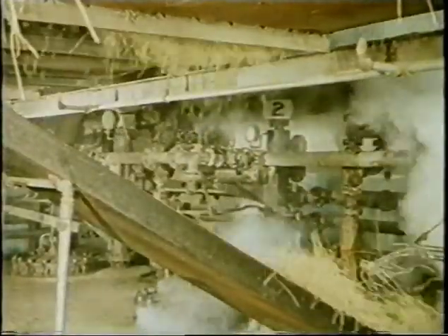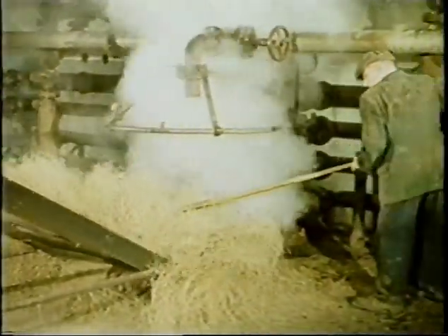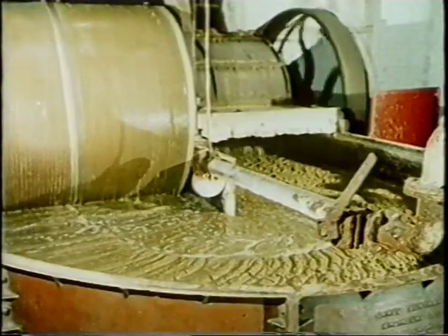One of the raw materials of paper is esparto grass, a tough resilient grass grown chiefly in North Africa. After vacuum cleaning, it goes into digesters, where it is pressure cooked in caustic soda solution. Caustic soda is made on the premises from sodium carbonate. It dissolves all non-fibrous materials and reduces the grass to pulp.